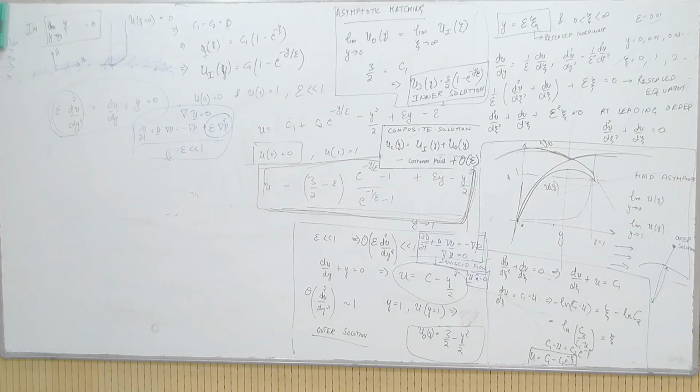But yeah, it's a very natural doubt to occur, that why are we doing this distinction between boundary layer and inviscid flows now. The only reason is that in low Reynolds number flows we had 1 by Re which was much less than 1. So instead of thinking of this equation like this, it was actually something like 1 by epsilon. Okay, so the whole situation was reversed.